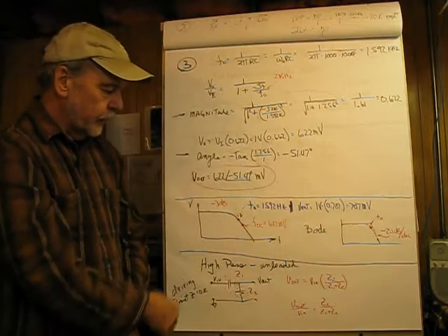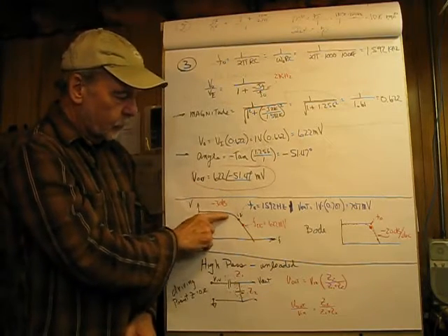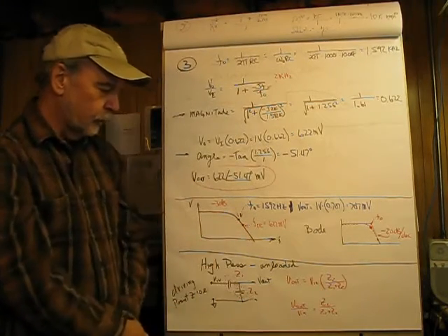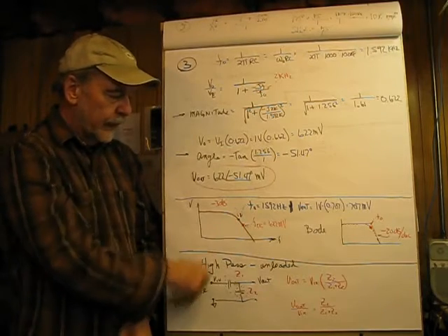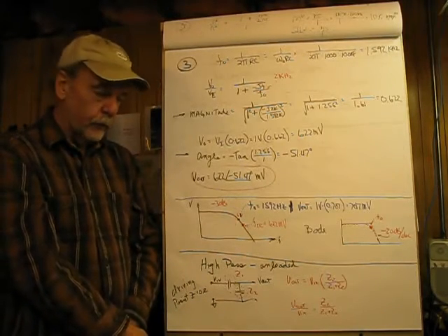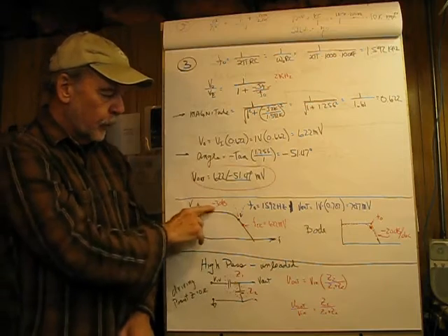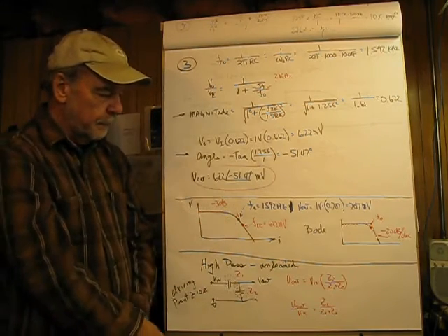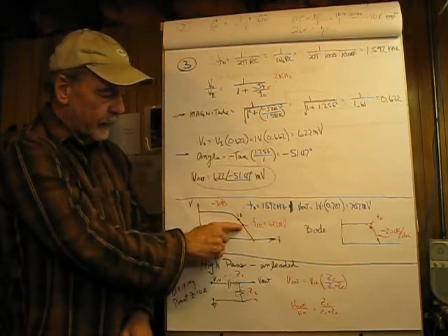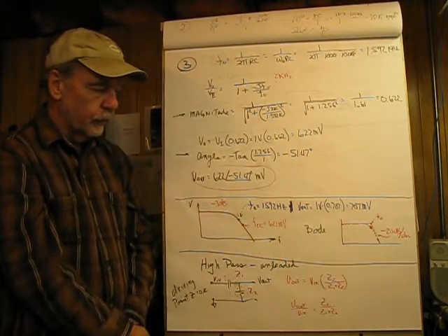So if we take a look at this, here we have our actual point-by-point frequency response in black, and I put a little blue dot there that represents our critical frequency, 1592, also the negative 3 dB point, and then our F at 2k comes in at 622 millivolts.